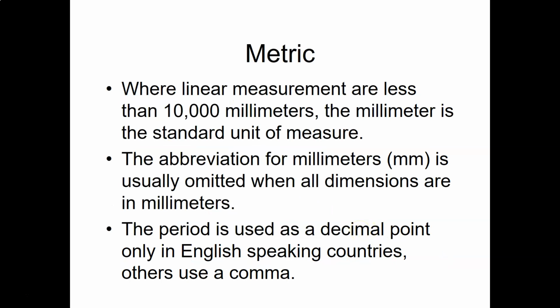Metric, well, our base unit in metric is millimeter. And believe it or not, we use the millimeter all the way up to 10,000 millimeters. That's our standard unit of measure. The abbreviation for millimeter is mm. And if everything on the sheet is a millimeter measurement, we do not put that on it.